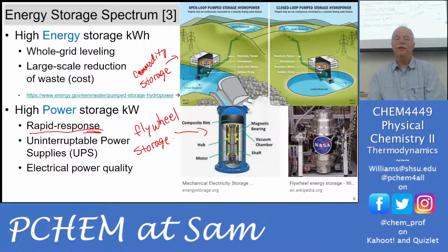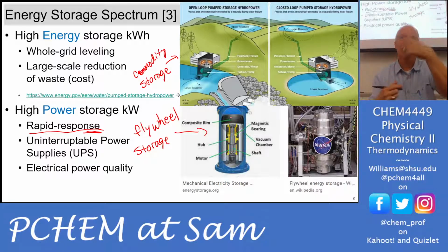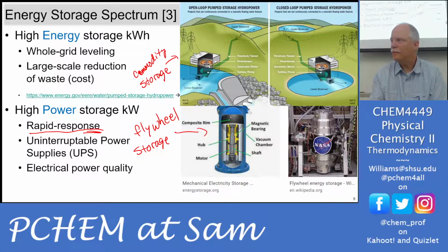I really love this flywheel idea. So you've got this device that's spinning inside, and you put electricity in it. There's a motor, okay, and it spins up this heavy object and stores energy in its mechanical motion, okay. And then when there's demand, you clutch into that and you spin a generator, and so the mechanical motion turns a generator, and you pull the electricity back out. So you're just storing electricity in momentum.